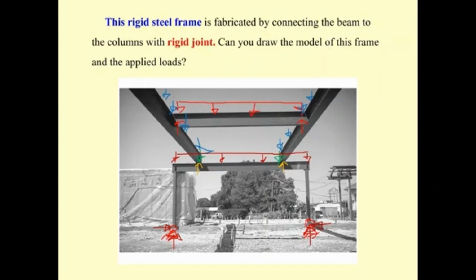Again, you may see on this frame the load will transfer to the cross beam here to be the reaction. Okay, and that reaction is transferred to act on the girder, and the girder has its own weight.